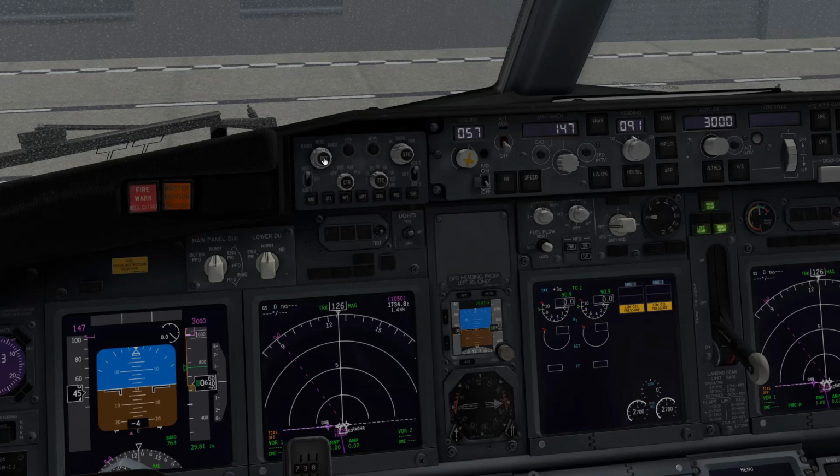764, and I don't want to see that on my altitude tape on takeoff, so it's not distracting. I'll just push that button and it's cleared. I can bring it back anytime just by pushing the RST button. Flight path vector, I usually put that on. I don't know if it works on this airplane or not. And altimeter we've already set. We'll use about a 10-mile scale on our nav display.